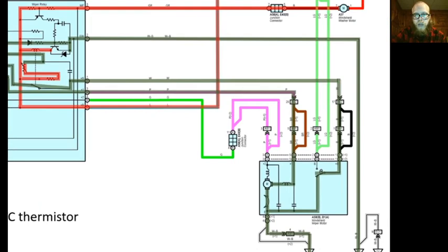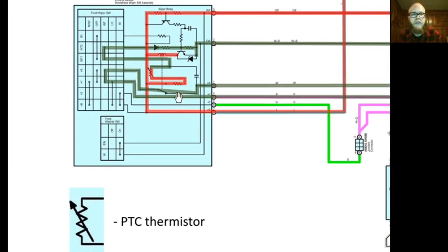We're in our parked position, so I'm attached to ground down here. So I need something to get the wipers to move a little bit so that then the parking circuit can take over and complete the wipe, and then we'll wait for the wipers to get nudged a little bit again. And this PTC thermistor is the whole ball game as far as that's concerned on what the little timer mechanism is.